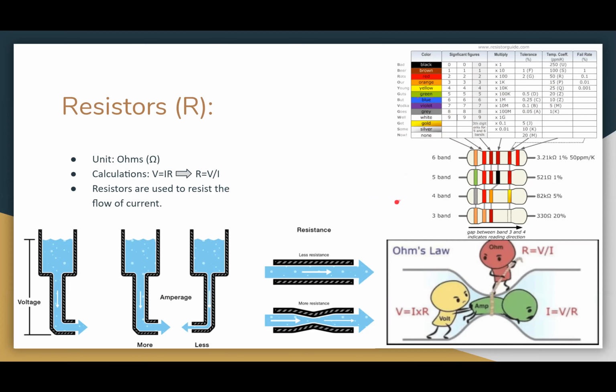Yep. So basically, that's what the resistor is going to look like. You'll see those colored bands. With those colored bands, if you check out those arrows, the far left ones give the significant figures. The first one is orange, so it's 3. The second one is red, so it's 2. The last one is brown, so it is 1. So just think of the number 321.